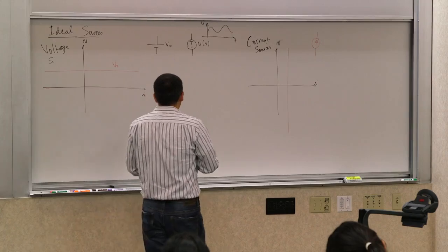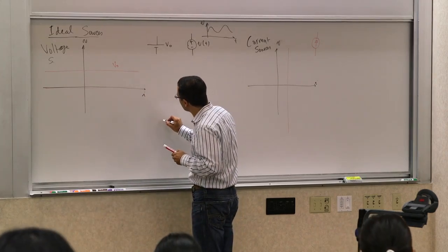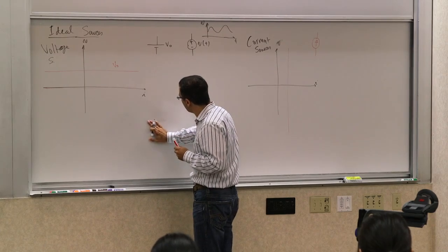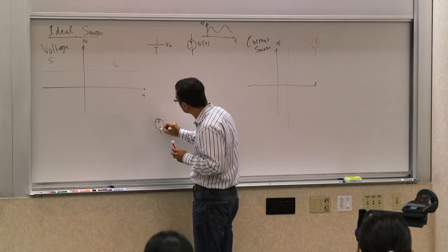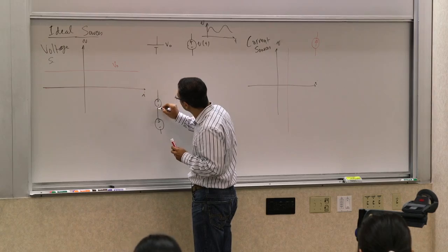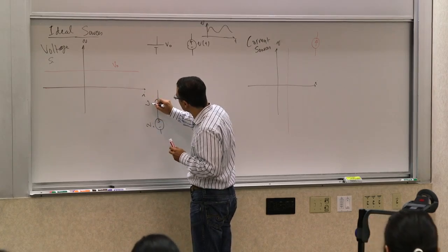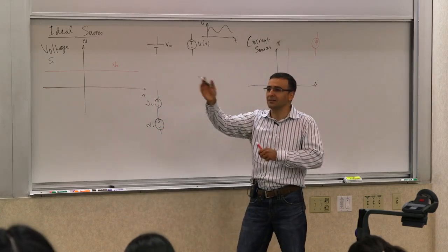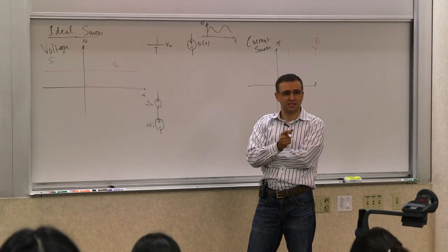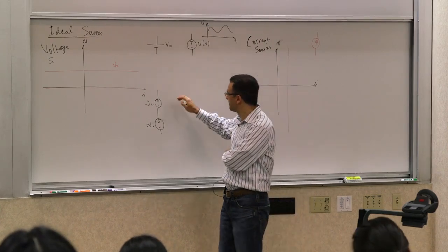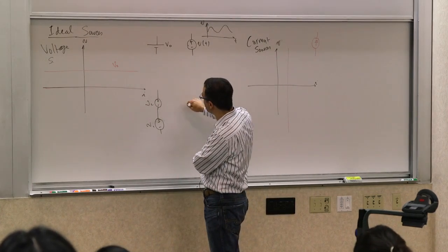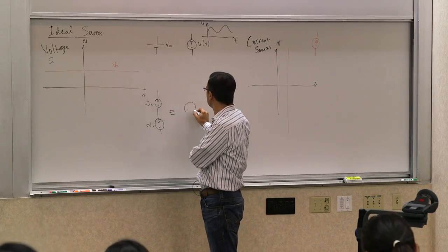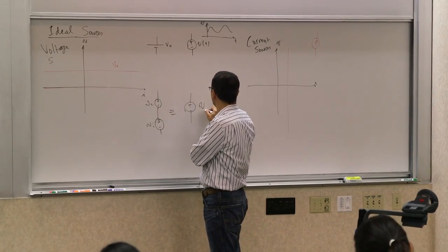So now, let's talk about voltage sources. If I take voltage sources, let's say constant or time varying, it doesn't matter. Let's even make them general. If I take two voltage sources or n voltage sources, V1 and V2, and put them in series, what is this equivalent to? Think about KVL. It's the sum of the two voltages, right? Because through any loop, you have to add these in series anyway. So this is equivalent to a single voltage source with a voltage of V1 plus V2.